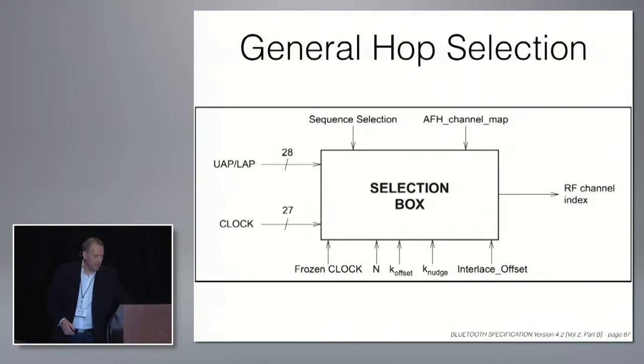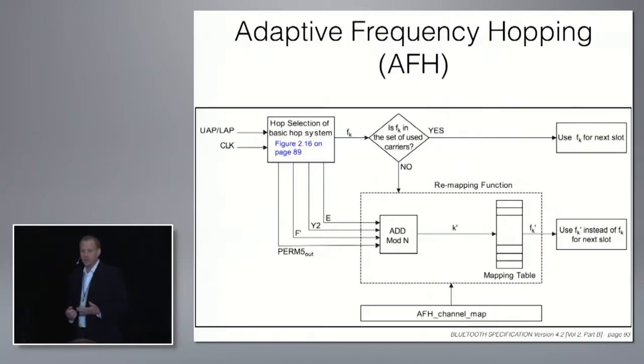Now what's really cool, again, another coexistence implementation, is called adaptive frequency hopping. Adaptive frequency hopping has mechanisms within the specification for slaves and masters to report to each other whether they are running into interference or other things happening in the time-slotted frequencies they're using. If there is, they have this reporting function where they can report that a channel is either a used channel or an unused channel.